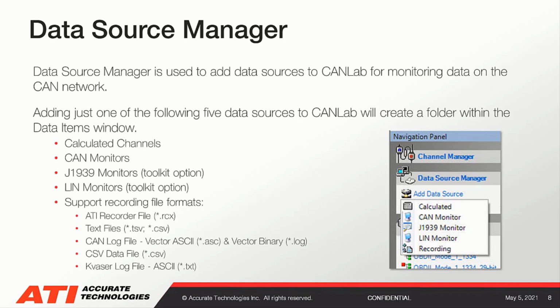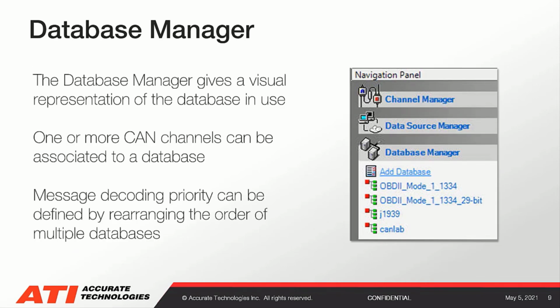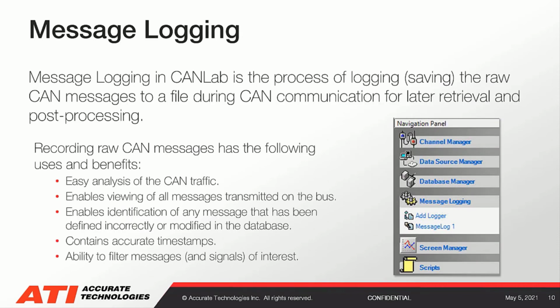Below the channel manager is our data source manager. This is used to add your data sources to CANLab. Multiple monitors, recordings, and channels can be added at any time that the workspace is active. Below that is the database manager. The database manager is where all active databases are added and organized for use in the workspace. Below there is the message logger. Message logging is the process for saving raw messages for later decoding and post-collection processing.